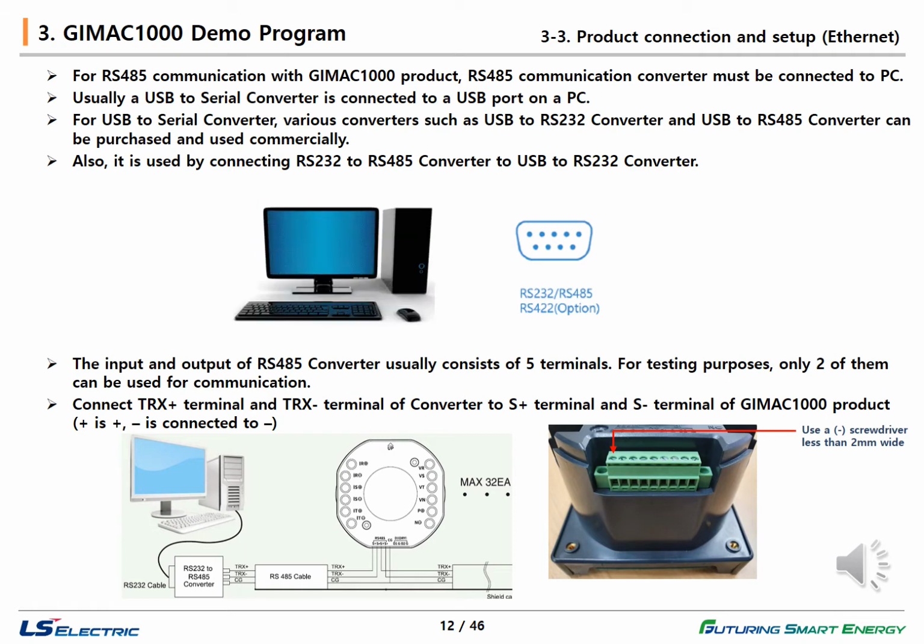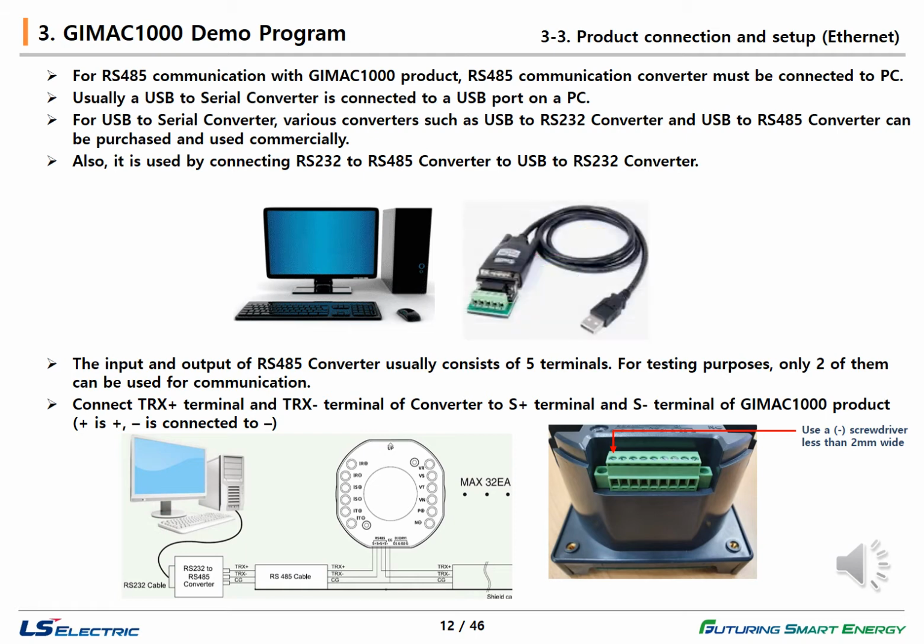However, in general, laptops and computers do not have an RS485 port. Therefore, you need to connect an RS485 converter to the USB port on the PC